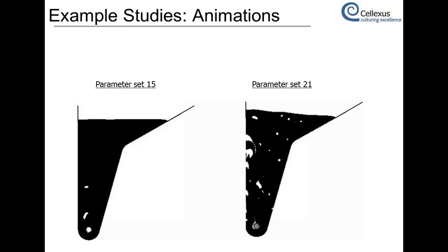So these are the sort of parameters we optimized for, and the idea was to make sure that we moved those bubble sizes and equivalent circular diameters down to below 20 millimeters but above 7 millimeters. And just to give you some idea of the trends that we observed, we found that obviously if we reduced the sparge tube diameter, the equivalent circular diameter was reduced.